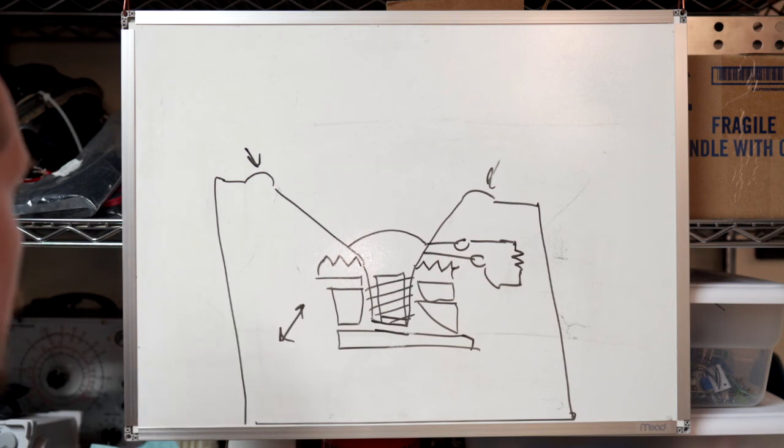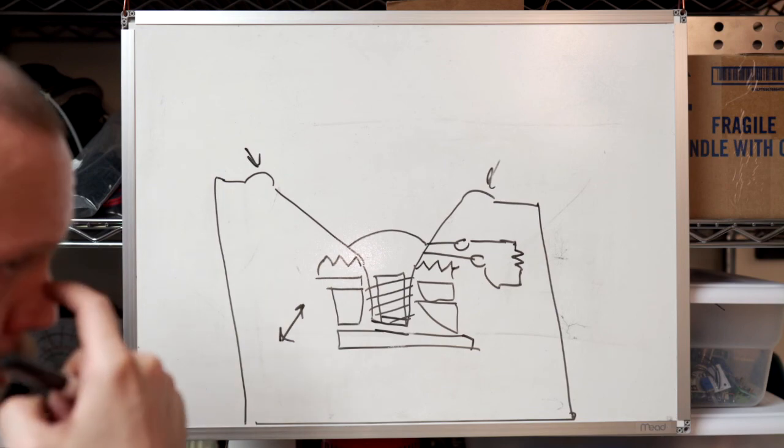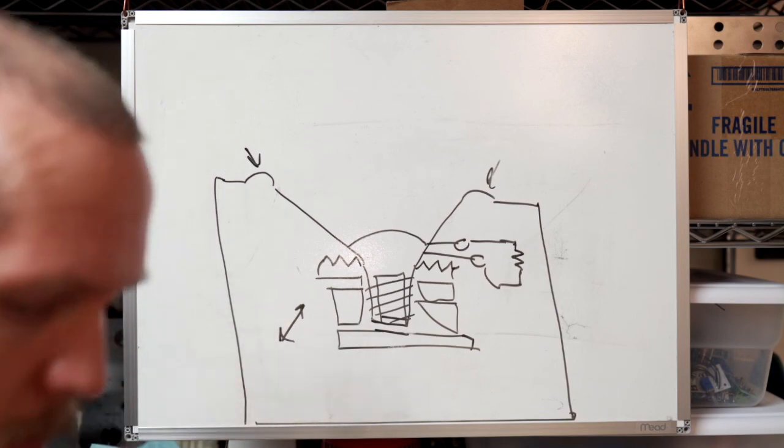And so, like I said, the output impedance will change your frequency response a little bit. It'll also change the dampening characteristics of your drivers, particularly your woofers, in the bass frequency range usually. And so that's sort of the briefest overview of output impedance and why you should care. All right, hope that helps.